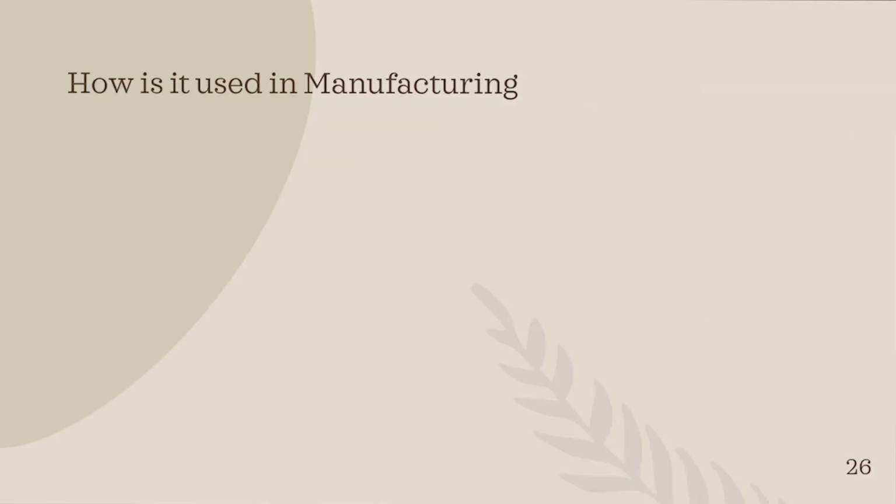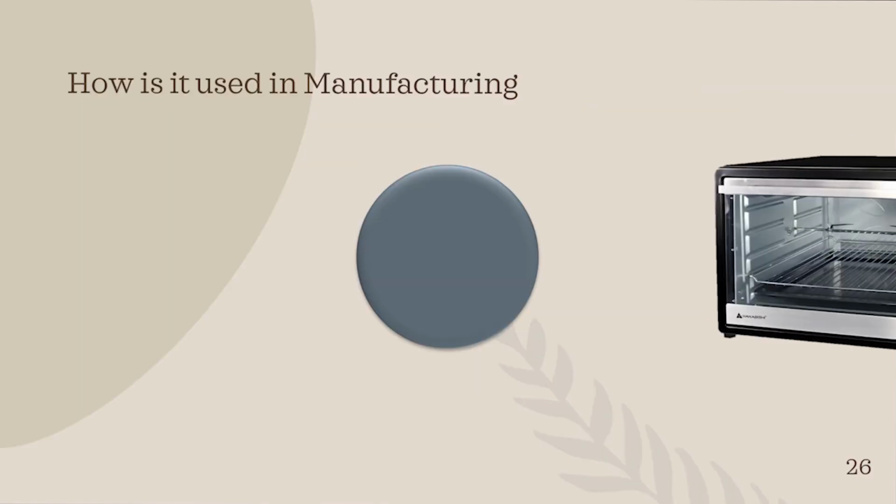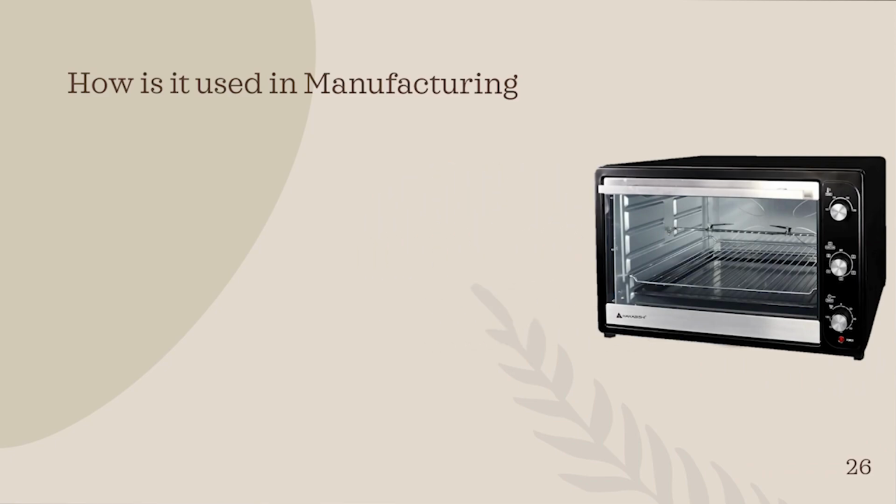So how it is used in manufacturing. We have our wafer. We have our wafer oven. We're going to throw it in the oven. Give it a second. It comes back out with our oxide layer. Pretend there's a photoresist layer as well. I forgot to put it on.